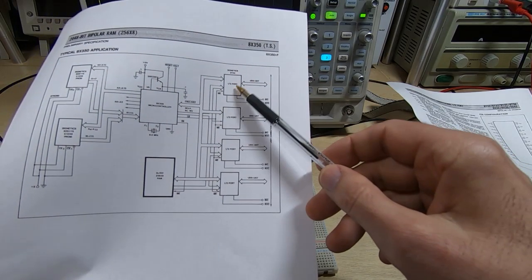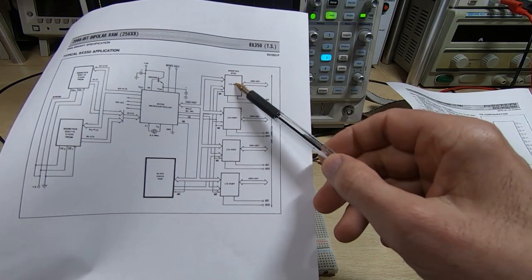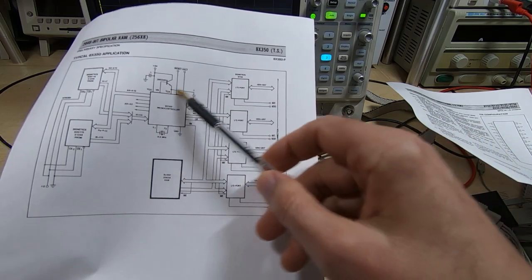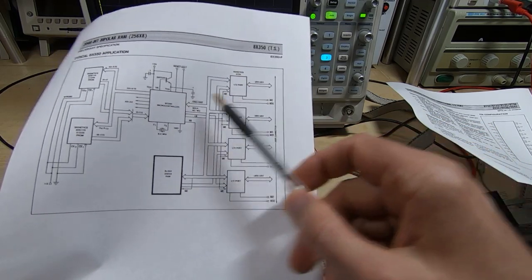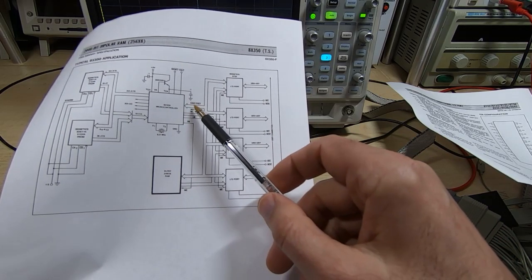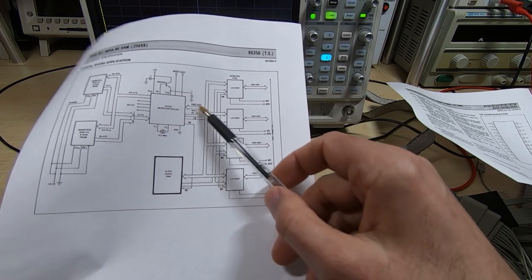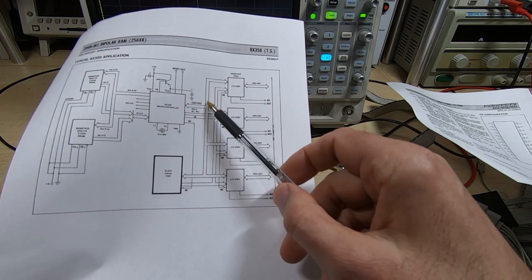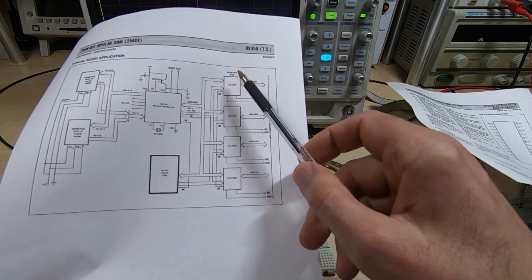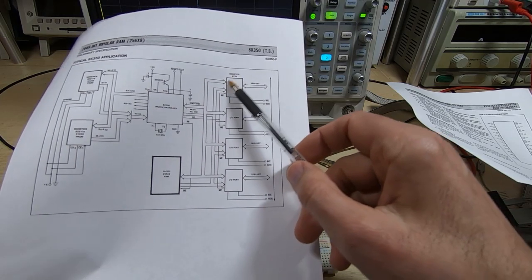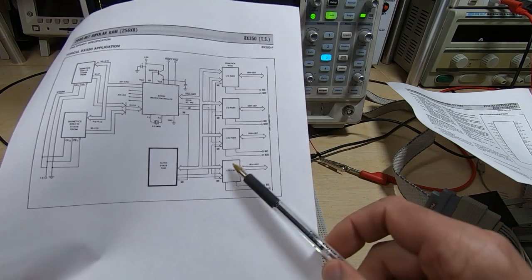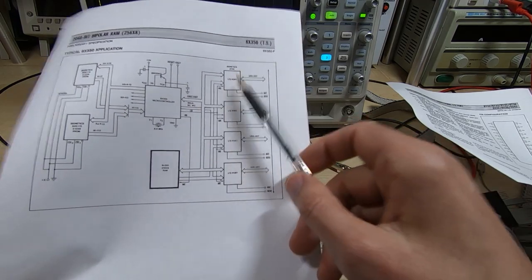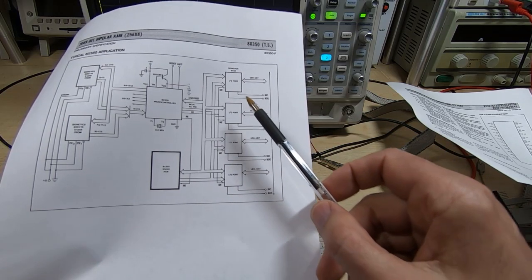So what you would do is you would order different address numbers, and the way that this processor accesses the latches is a 2-step process. First, and this is an 8-bit bus, the first 8 bits are an address. It sets that address up, and it effectively forewarns whichever port has a matching address that it's about to send or request data from it.